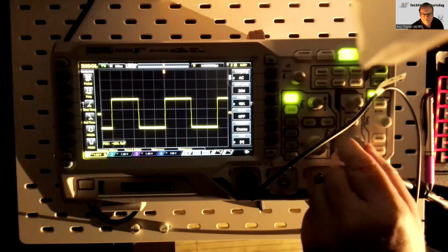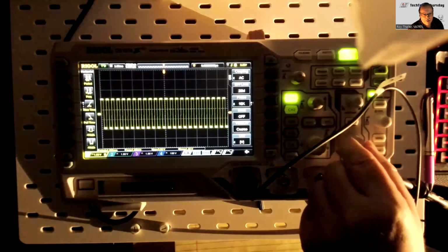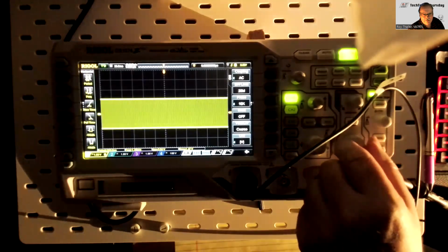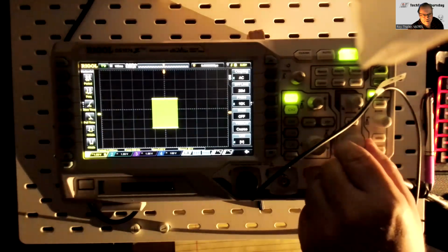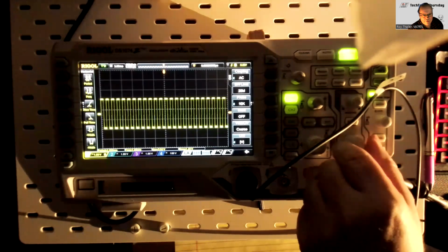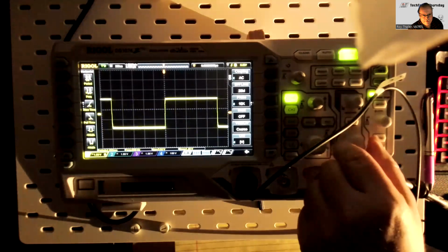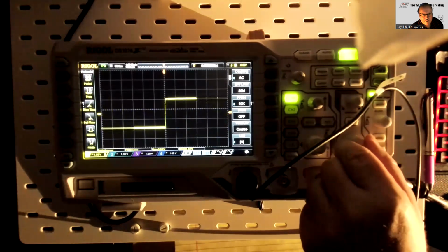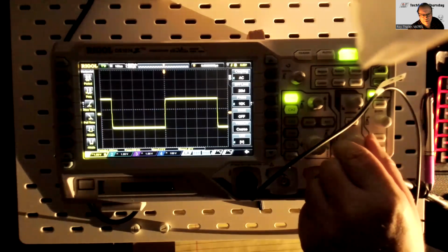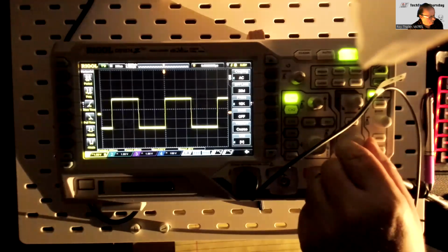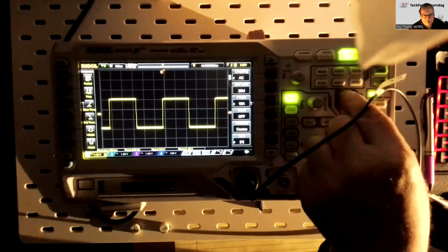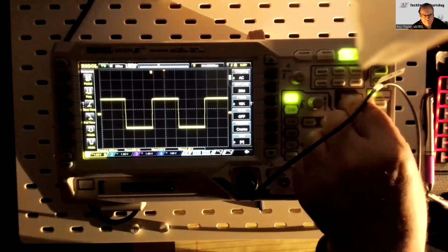And then over here is your frequency control. When you look at it, this is what you see. You can see there's a whole bunch of cycles. Then you have to decide what you want to look at in terms of the waveform. Here is typically one cycle. But if you wanted to look at the edge in more detail, or if there's some noise on the edge, you could look at it that way. So you've got that control. And then again, you've got positioning here where you can move things up and down.